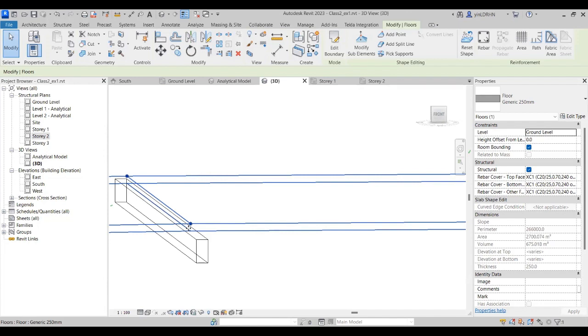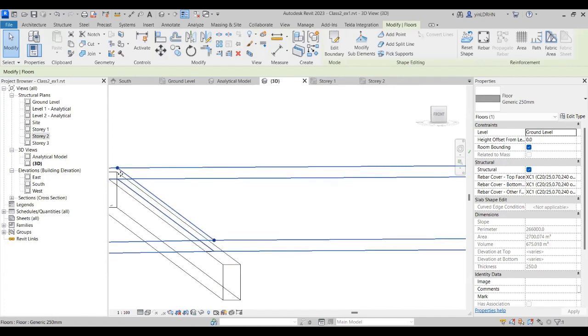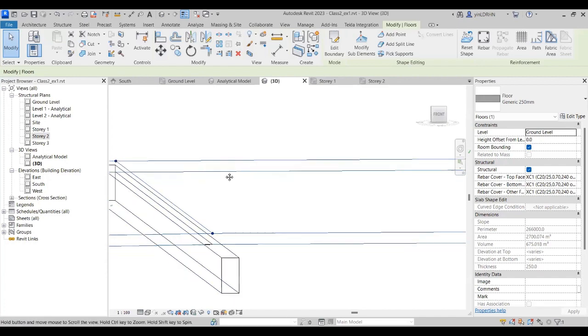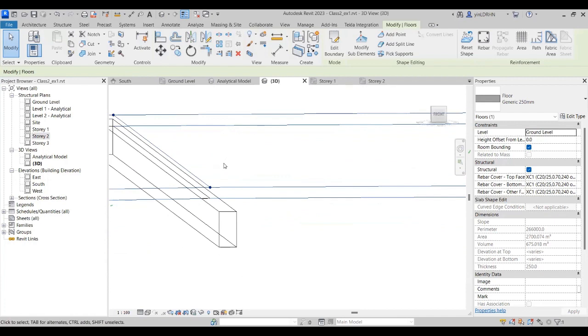We cannot exactly do the same thing in the analysis, right? Even though we put that slab on top of the beam, when you do the analysis, the line should be the same center line. Otherwise, the software cannot understand, right? So that time we have to do some modifications. I'll come to it later on because there's a way to do it actually. That's one called analytical link. You add a link and so on, right? But it's very complex for a normal beam slab system, but we can do it.